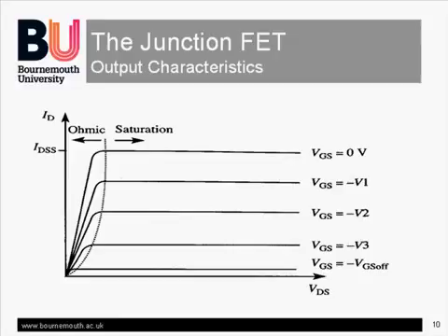However, the transistor is mostly used in the saturation region. Here the channel is pinched off at the drain end by the potential difference between the negative gate voltage and the positive potential gradient in the channel. The drain voltage has negligible effect on the drain current in this region. The graph is essentially, although not quite, flat, but the gate voltage is in full control, with the output drain current increasing as reverse bias on the gate reduces.